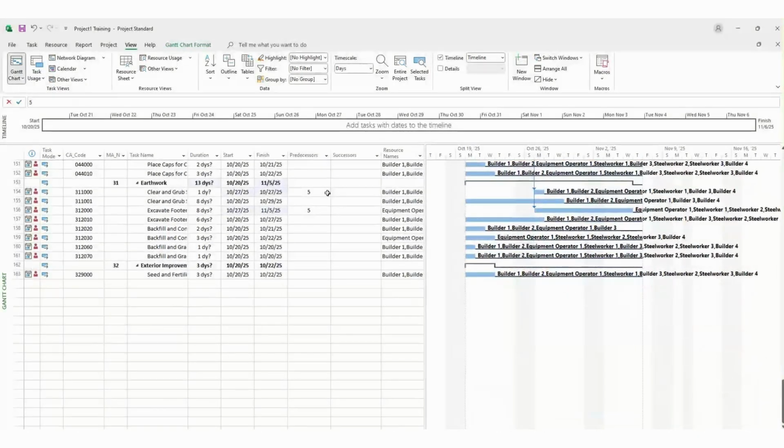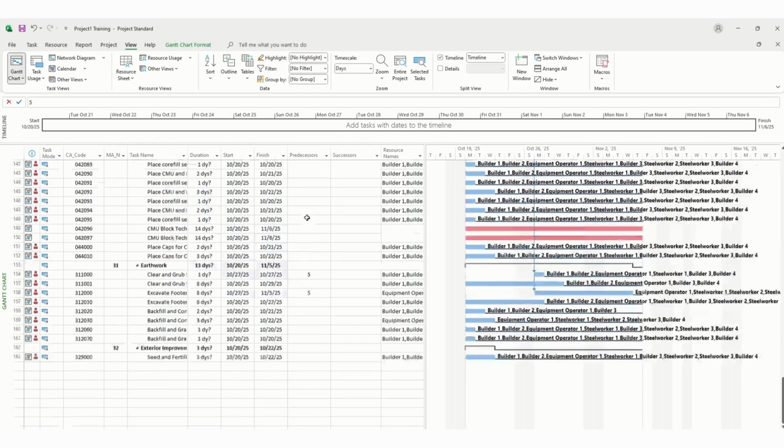Now let's say I want to do the excavation, right? But at the same time, I want the successor to be backfill and compact. Well, this is a long footer. This project, each section is about 400 feet long of footer that they're excavating. Well, I don't want to keep a 400-foot hole open the whole time. So I want to backfill and compact as I'm going. So the way you can do that is you can get backfill and compact to also be predecessors number 5.